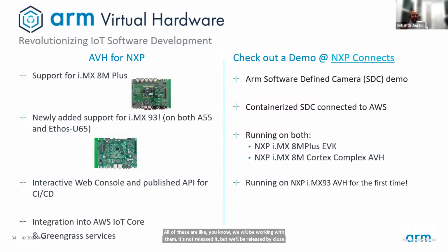Fantastic, thank you. And can you select between running a single core A55, dual core A55 on any of the packages? So the i.MX 93 1, 33, or 30? Yeah, definitely. It can be done through the software, and all of these different ones, the 935 as a single dual core option, 931 and 933 and 930, all of them have single dual core option. And from the BSP, the software BSP, you would be able to select the cores that you want to activate.